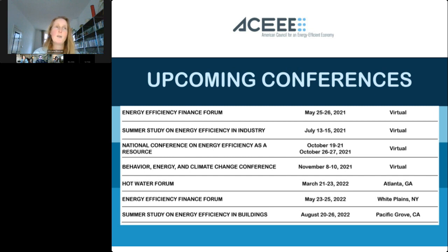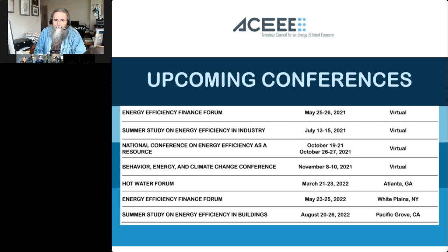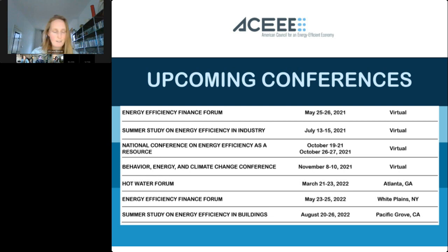So depending on pipe lengths, pipe diameters, pipe wall roughness, and the demands, and also the pressure that is available, it will show you how the water flows through the system, at what speed, what is the pressure that you still have left at your shower, etc. And that one's from the US EPA, actually. It is, yes, it is. And that is also open source. Everyone can use that.